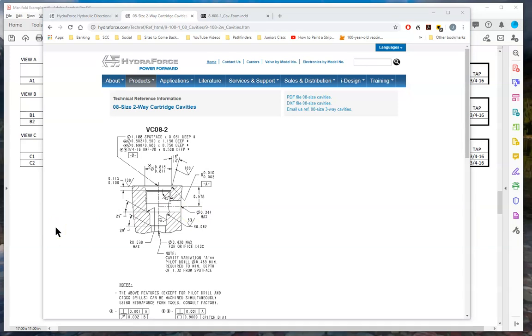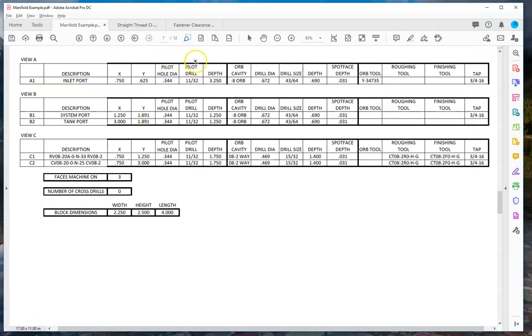So if I go back over to my negative build sheet, that gives me that information, and it tells me what depth to do it. This first block of information tells me where to locate the hole and what size hole to make. If I look, all of these holes here happen to all be the same size using the same drill, but they're at different depths. The next thing I do is move over and say, well, what is this?